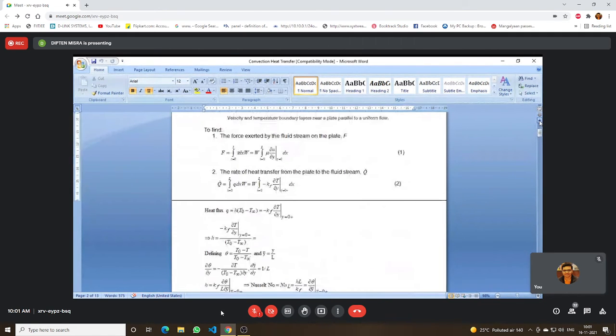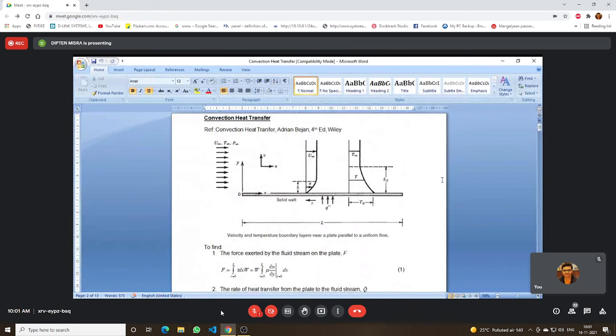you have raised one very interesting point. If it were an isothermal flow field, with no change in temperature, then the density could have been constant. But the moment we have different temperatures at different points, the density is going to change, because density is a property that varies with pressure and temperature.